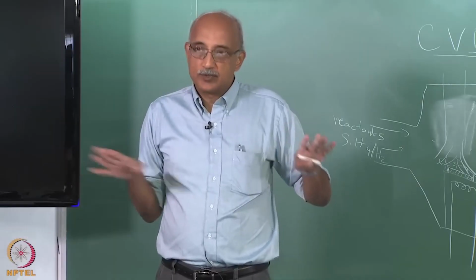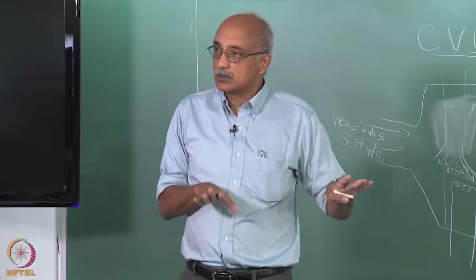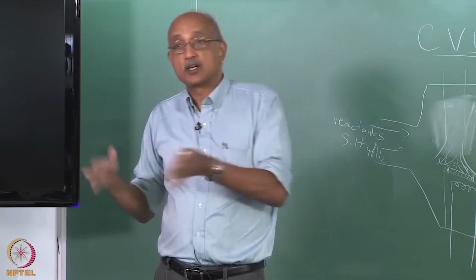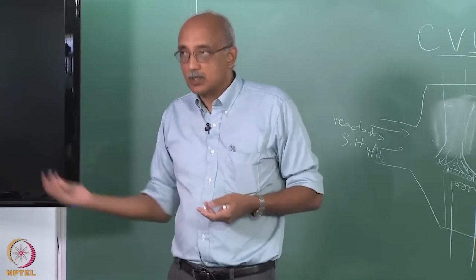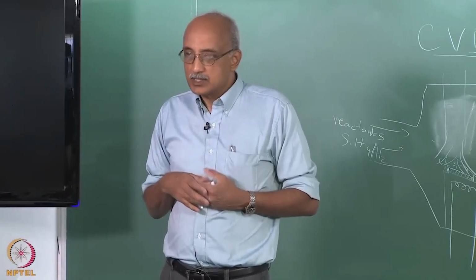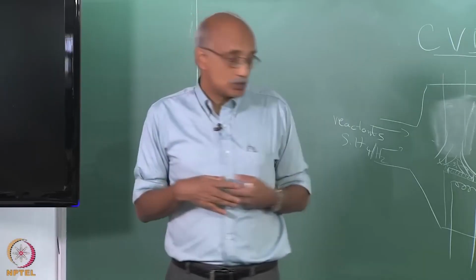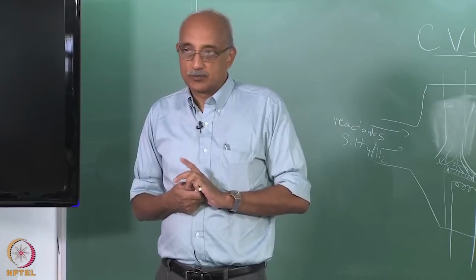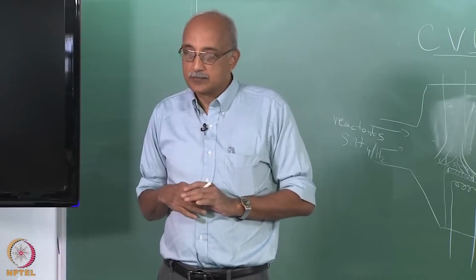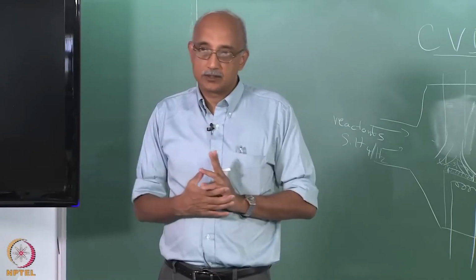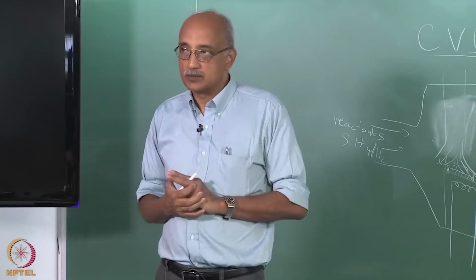You do not want the prevailing Reynolds numbers to be so low that you are essentially in creep flow conditions or stagnation conditions. You do not want it to be so high that you are in turbulent conditions. So, you want to operate somewhere in the middle where your Reynolds numbers are reasonably high to ensure that the convective transport is happening at a sufficiently high rate, but at the same time the Reynolds number should not be so high that you slip over into the turbulent regime.